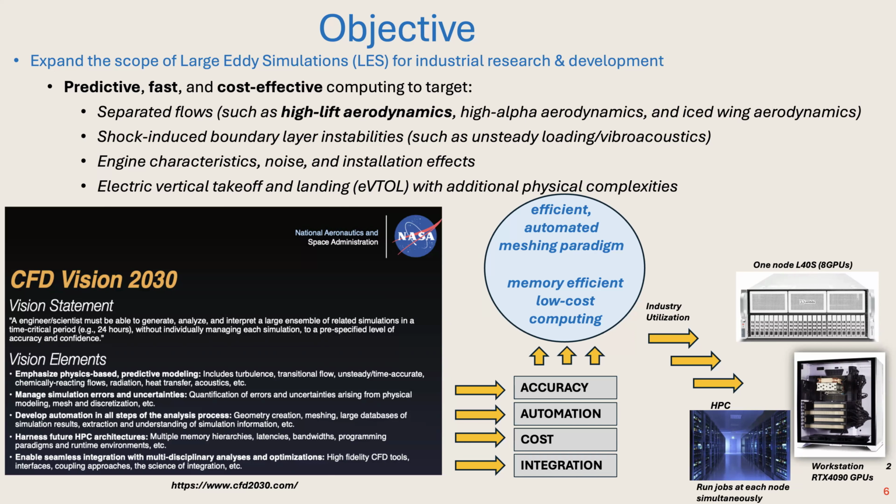Number one is we have to deal with an efficient automated meshing paradigm. And I am proposing a Cartesian octree, not only in terms of generating it quickly, but also it gives the ability to do grid resolution studies in a very short time. You can do grid resolution studies simultaneously and then check-mark this verification process in a couple of days instead of multiple months.